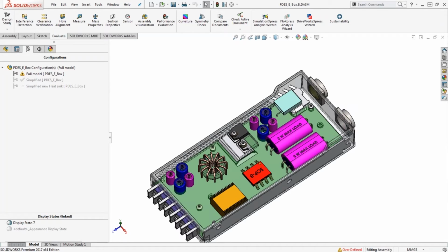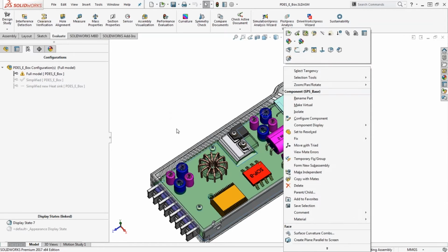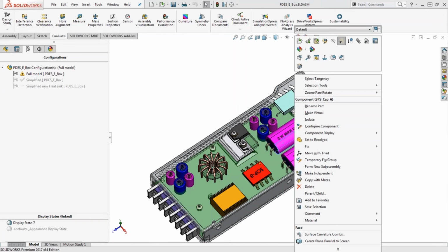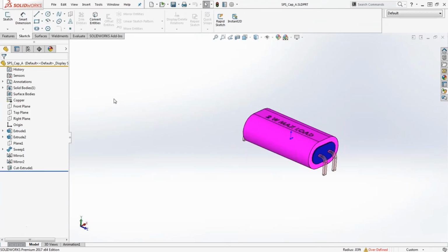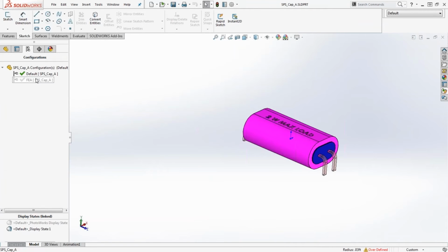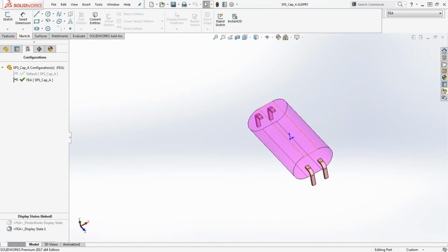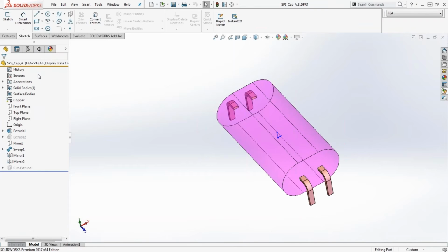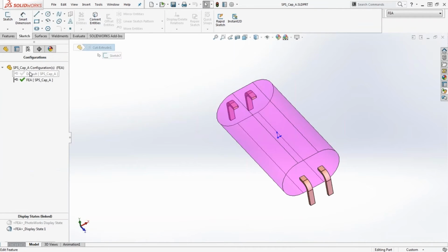a failed mesh because the mesh size is just way too big to try to account for this small level of detail, right? And ultimately, those details are just not going to have an effect on your overall results, whether you're running a structural analysis or you're running a thermal problem. All you really need is the overall general shapes.